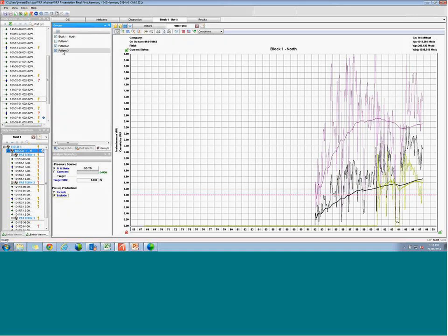Using this VRR plot, looking at the aggregate of all of them and looking at every single pattern, it can help give you information into what might be going on in certain patterns. Are you over-injecting, or was the reservoir characterization done wrong? Should we add different producers to this pattern? Are there too many injectors that aren't a part of this pattern? Are we losing injection fluid somewhere? It can help highlight where you may have issues.